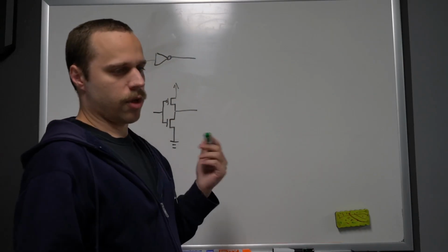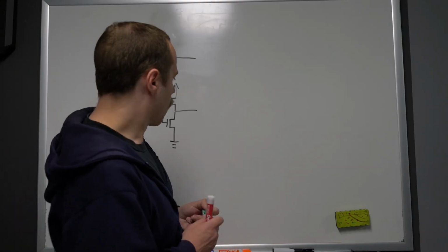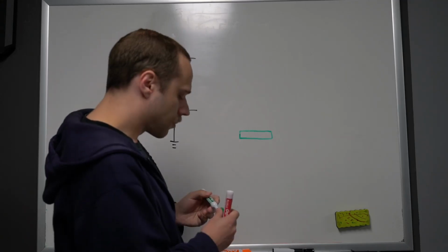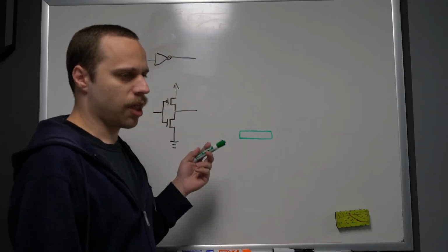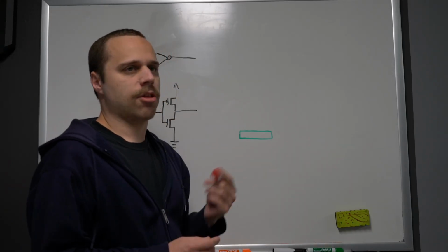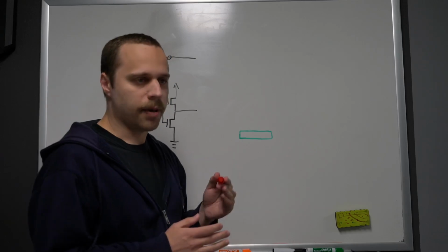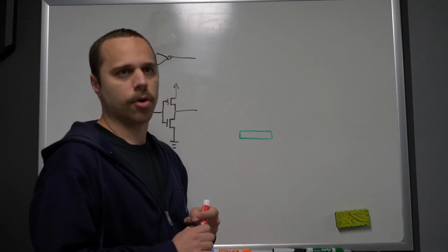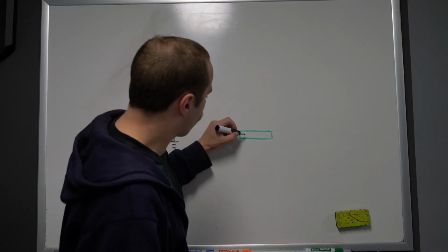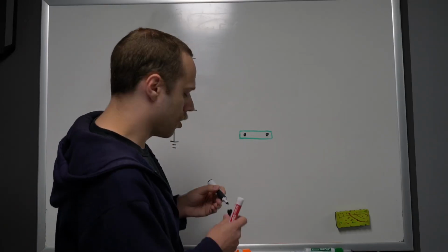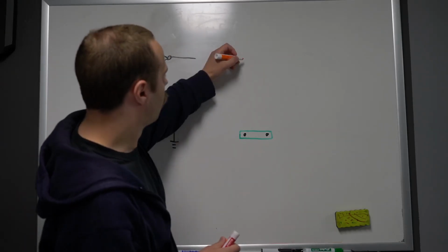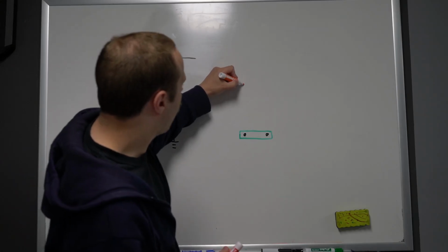So now that we've looked at a single transistor, let's look at the entire inverter cell. So we're going to start again with the NFET at the bottom. And these are, by the way, roughly the same colors that I'm going to be using in my tracings. They're somewhat based on the classic color scheme from Mead and Conway. I've tweaked it a little bit just to be a little bit more readable on modern displays and so on. So anyway, we've got our source and drain, and we're also going to draw contacts up to the metal layer for those. And so that is our NFET, and now we're going to add our PFET up at the top,